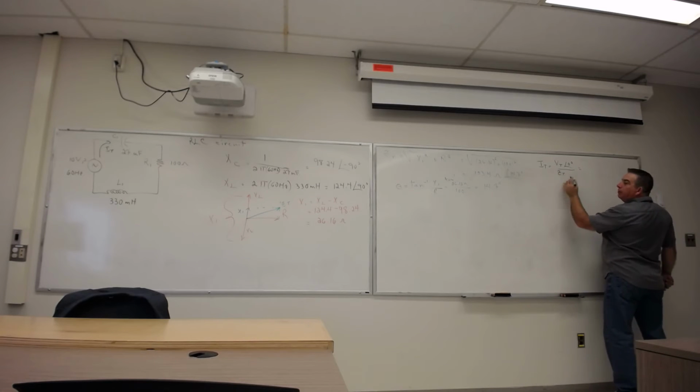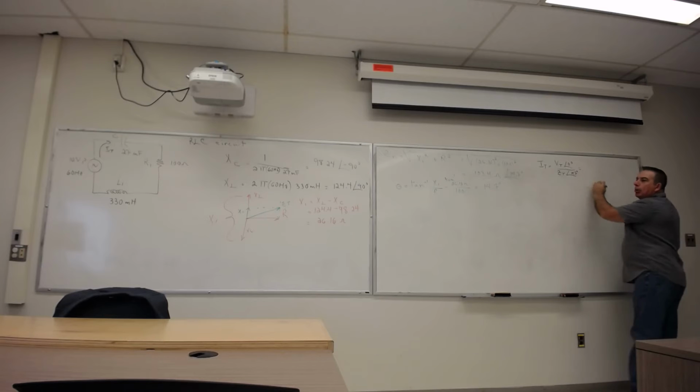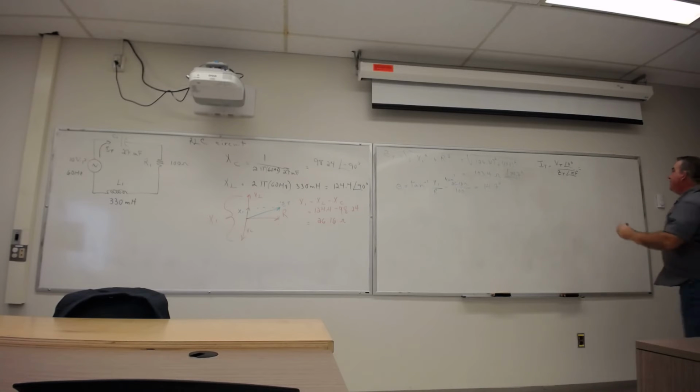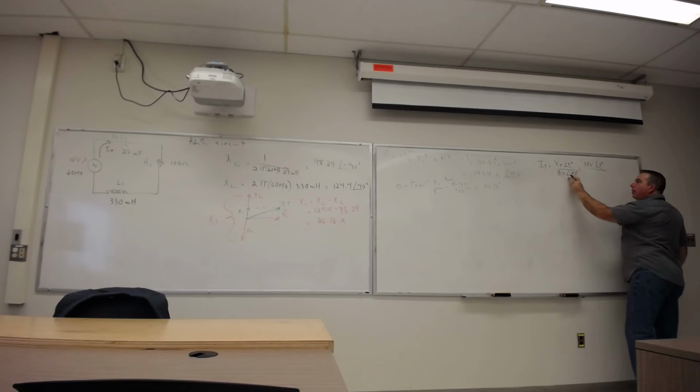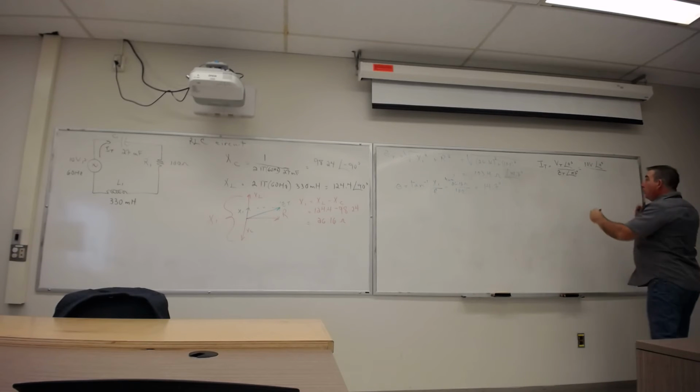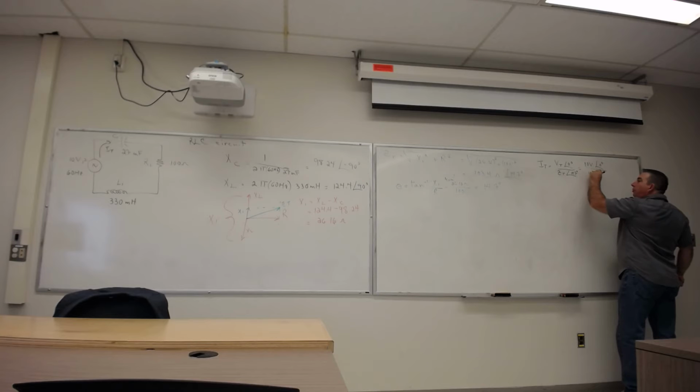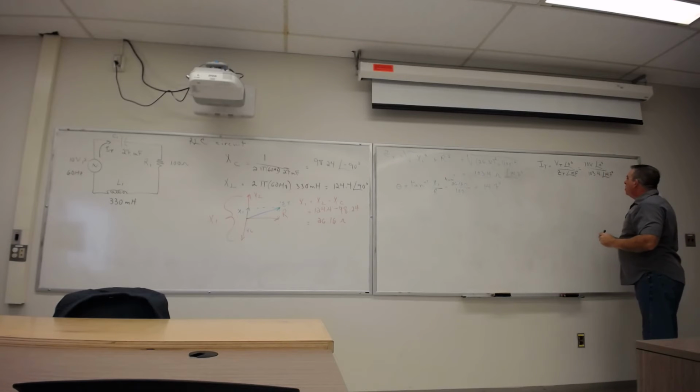So in our total impedance, we know that the total impedance is at 14.7 degrees. So we go, okay. Our total voltage for our circuit is 10 volts at 0 degrees. And our total impedance, we just figured it out, is 103.4 at 14.7 degrees. So we got a pretty good idea.